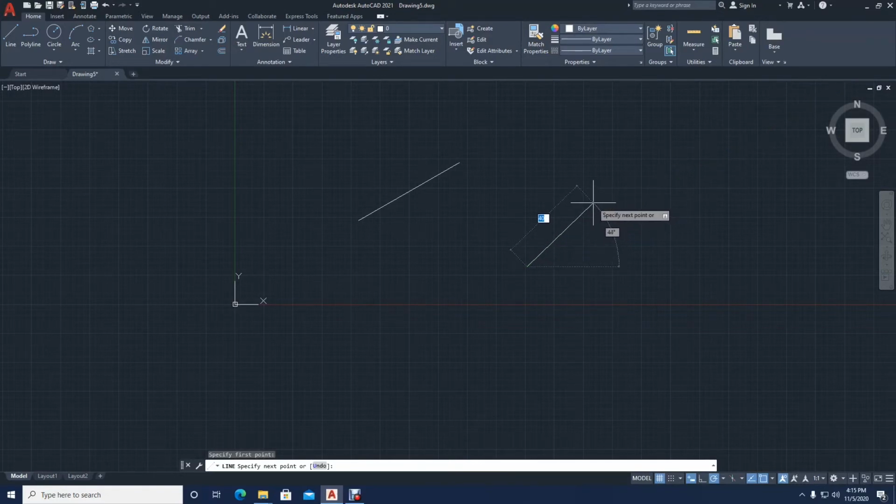Now, as you move the cursor along, you're seeing different angles, 49, 50, 51, but those are not definite, those are not specific. If you click it, it won't be exactly 53. The reason why you're not seeing 53.1, 53.2 going up is because my angle precisions were set to 0 decimal places. Now, once it gets to the angle that you have set, you will see the line.